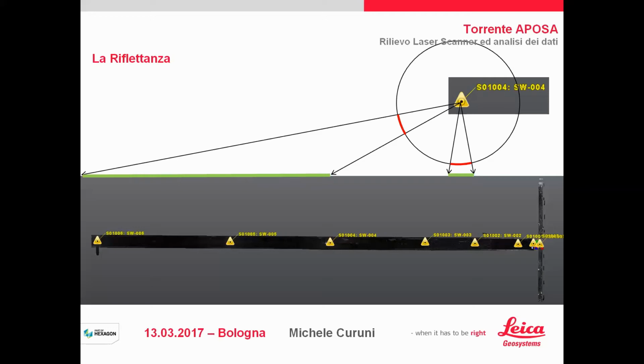two words about the resolution. Resolution in terms of density of points, the density of points of every terrestrial scanner, not only one brand or another brand. So today every 3D scanner works rotating 360 degrees in the horizontal and vertical direction, okay? So the resolution, the density of points, is set so that you can fix this resolution on the sphere that has its origin at the center of the scanner.